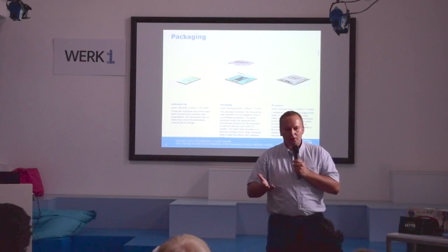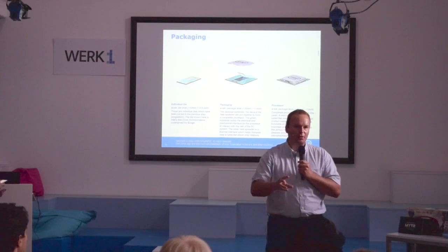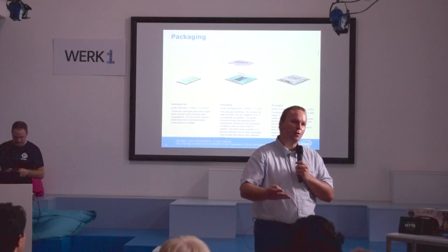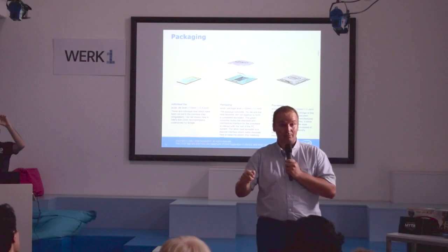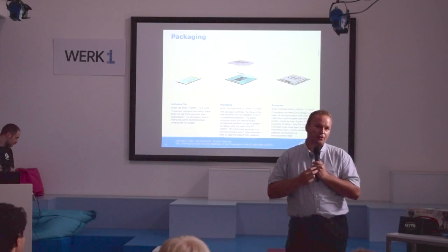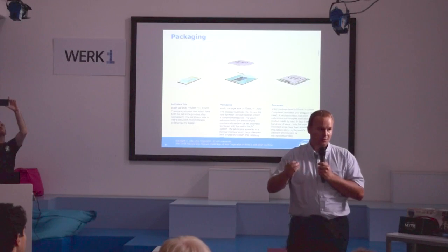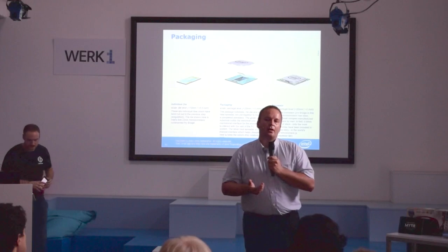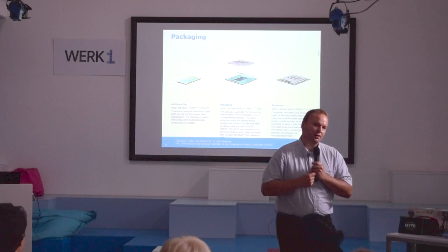As a general rule, you could say that depending on the number of cores, that's a good indicator if it's going to be from the same die or not. So if you have a 4-core i5 processor and a 4-core i7 processor, chances are pretty high that this is actually from the same silicon die, but with a different outcome in the manufacturing process, or in many cases when our yields are really good, and yield is basically a number of how well our manufacturing works, it's mostly then just naming them differently and charging differently.